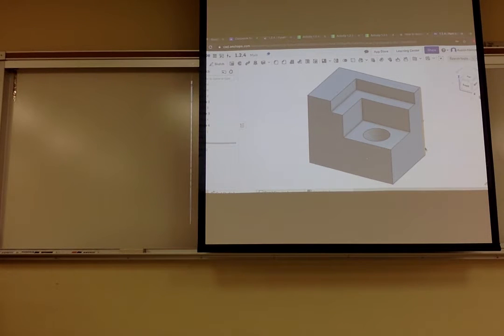It's like a ghost line. What I'm then going to do is place a point on my line. You see that it popped up as a square? That's telling me that's my midpoint. Then you can do something called a sketch constraint. I can say I want this and this to be coincident, in line with each other. That's how you would do that.